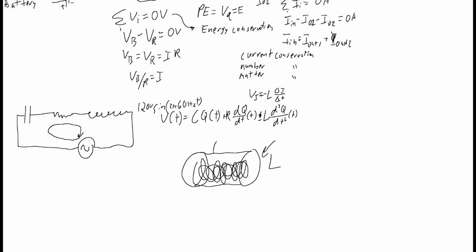But if we put a big old capacitor on the side here, we wire in a capacitor, a big electrolytic capacitor in here. It's in a cylinder, and they coil up the plates in there. They put this capacitor here, and what they do is make sure that the frequency of this system, one over root LC, is equal to 60 hertz, because this is most efficient.